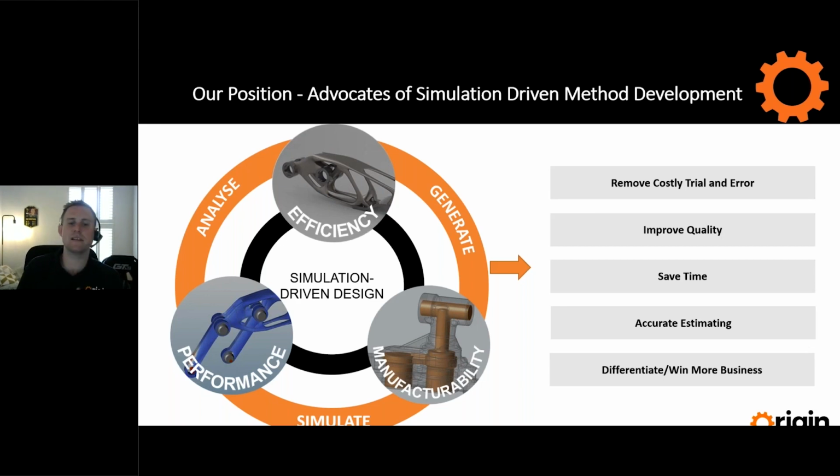As well as eliminating defects, we can obviously allow designers to explore multiple concepts, multiple ideas, different gate positions, different techniques, different materials, and we can allow them to do that in a safe space. Often we find that in the absence of simulation, in the absence of validation, you do tend to over-engineer a method to make sure it's safe, to make sure you get it right first time. So hopefully we can allow more concepts to be explored quicker and lead to better outcomes.